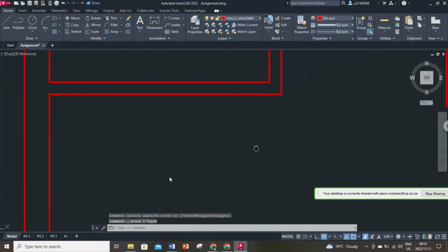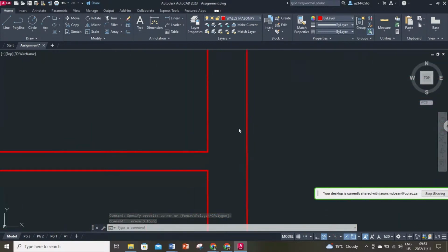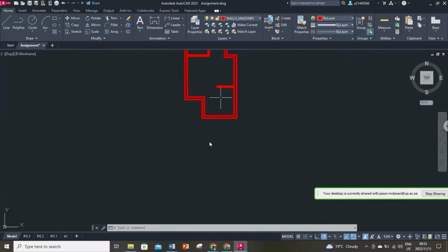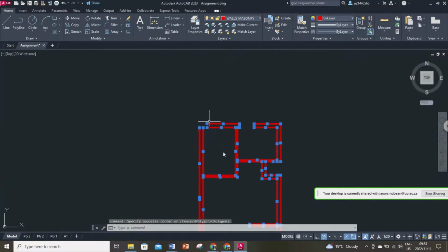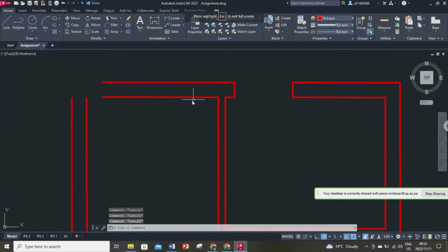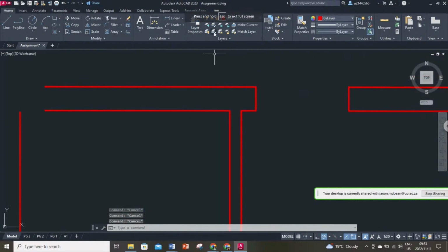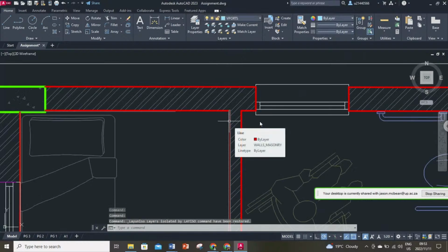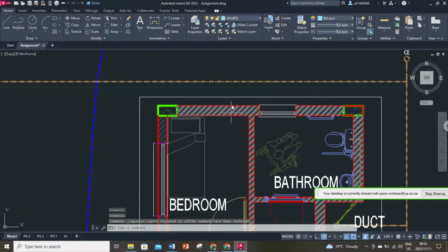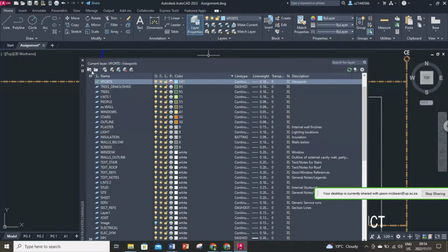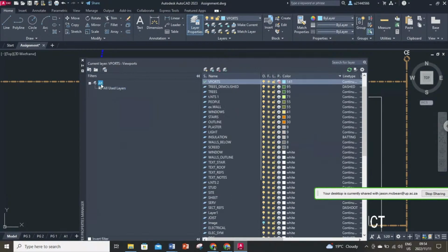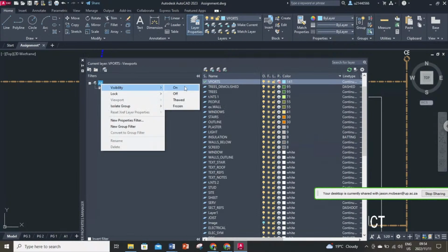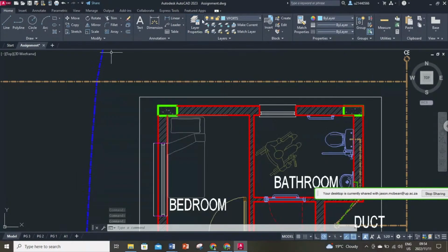Now you can go and see where you need to clean up, open where the walls go. Okay, so this is way better. Here you can also make sure everything is by layer, for example, especially for the walls layer. Then if you want to bring everything back, you just simply do that. Okay. Now, sometimes it will not bring stuff back. So you have to go to layer properties. You'll have to go and click on this all icon, and you can just say visible. It'll switch all of them back on very quickly.